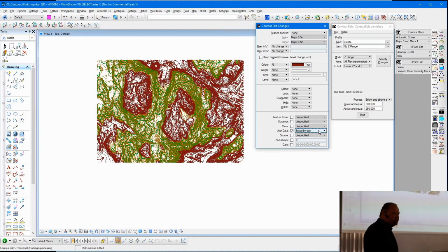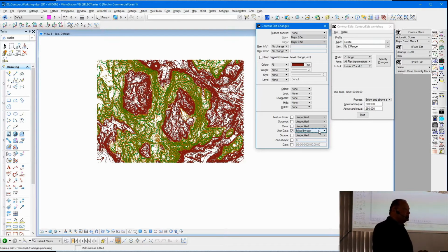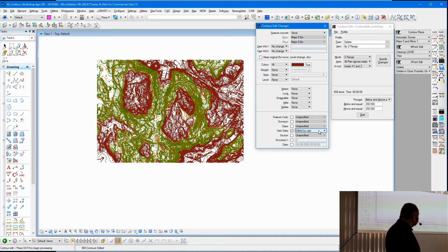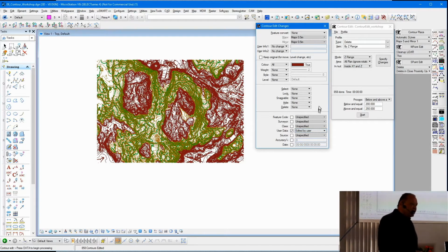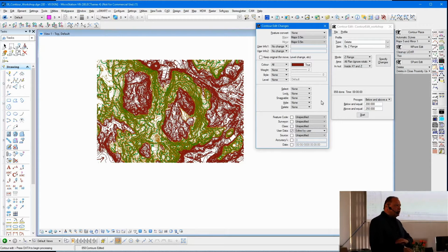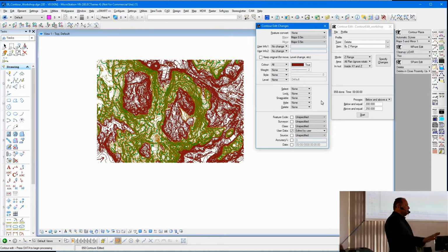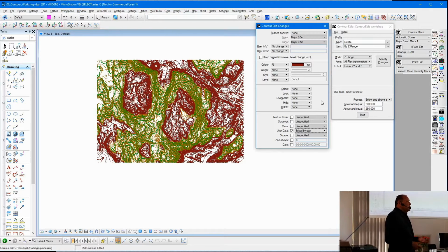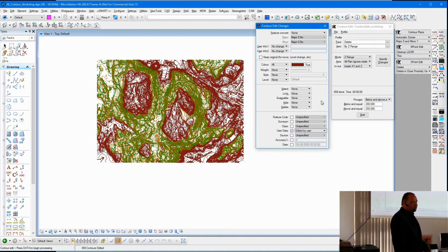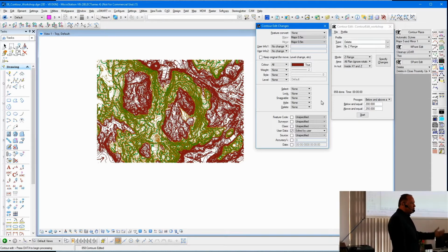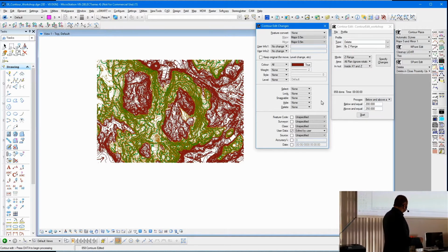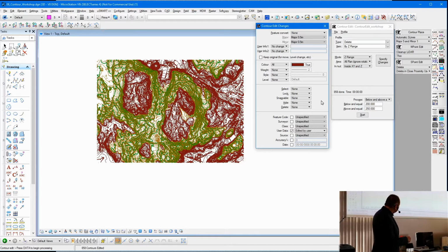You go and enter a date, and you just simply create a new type and item and say replace date. You enter your new date over there, not as the default, and run through the whole job, and it fixes the date for the whole survey. Because imagine if you'd put the wrong date in. Now, how do you do it? Start over again, go and do my survey, all my contours over? No. You just come and change the date over here. You switch on that button over there, and you say, I want to change the date, please.